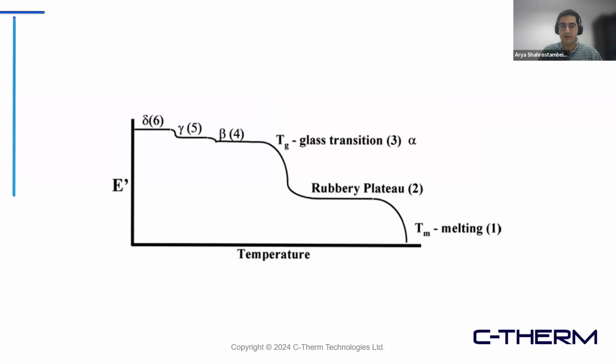And more than the typical temperature profile of your material, when you're at lower temperatures below the glass transition temperature, the glassy state, your material gains more mobility. You'll have three different stages of changes in your material. For example, there is the alpha temperature for a transition, which is the glass transition. And before that, we have three different temperatures. Beta is the temperature at which the side chains of the molecules are moving.